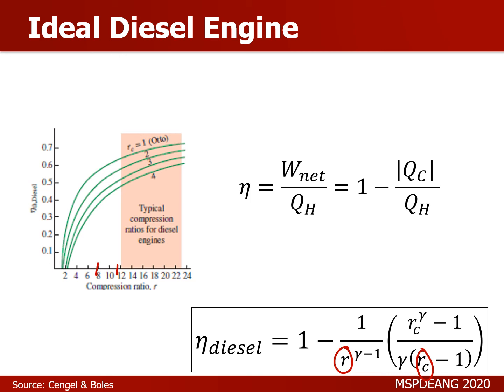Now, the downside to diesel engines is that since we are relying on heating the air for instantaneous combustions, one problem for diesel engines, especially for colder climates, is that the ambient temperature of the air may be extremely cold, such that even if you compress your air to much higher compression ratios, hindi pa siya aabot sa auto-ignition temperature ng inyong diesel or yung fuel. Okay, so with that, diesel engines also referred to as cold start.